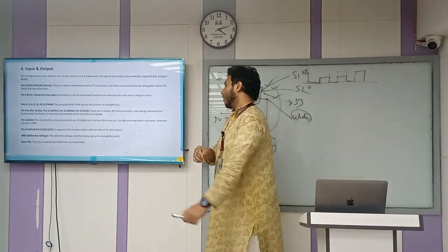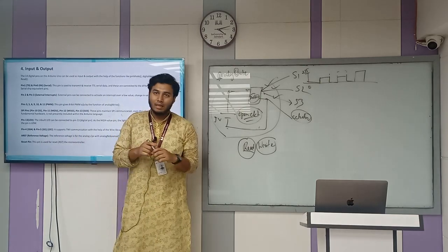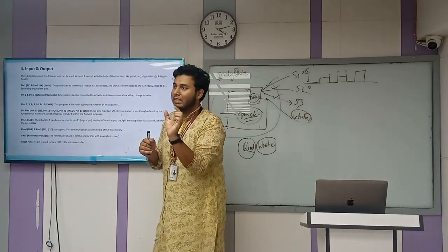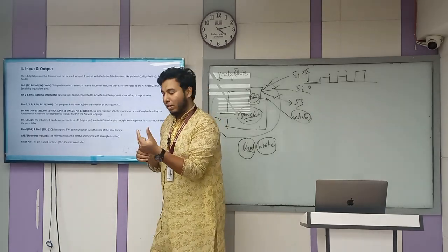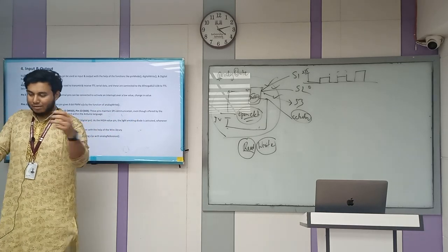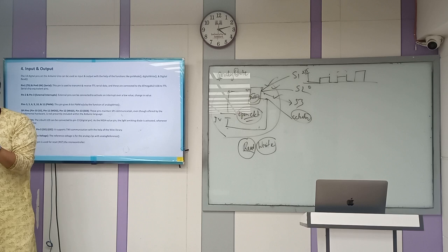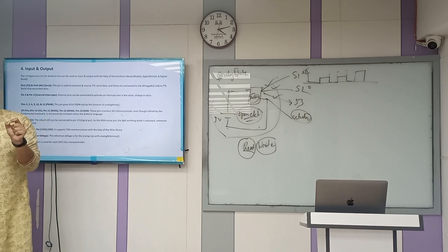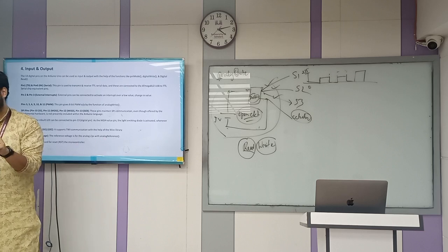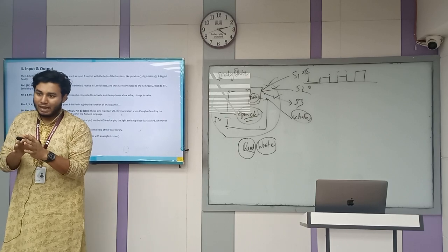Okay, fine. So there's another pin group, I2C. I have talked about that, SDA and SCL. This I2C plays a very crucial role in our daily life. A basic example is the LCD display. Previously, just a few years ago, you had to connect 8, 10, 12 pins from the LCD to the Arduino. If you connect that to the Arduino Uno, your pins will be used up, like there's no space or gaps left to connect even an LED. So you can do more tests with I2C.